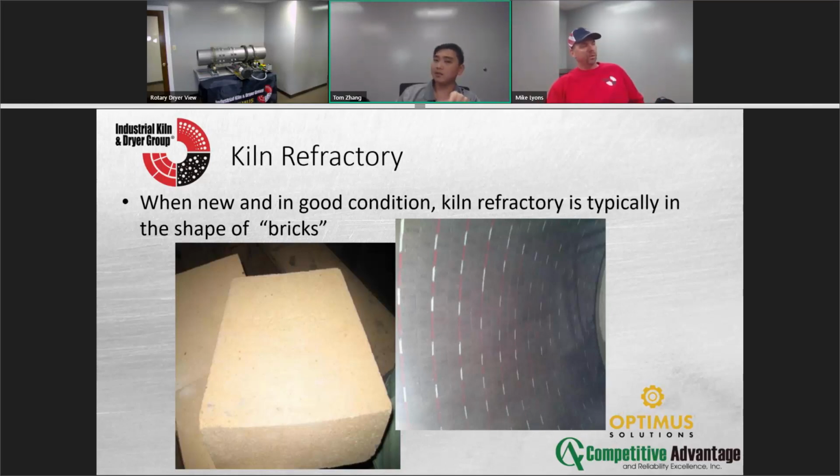I think I talked a little about it last time. You did. Make sure to look at your loads, because on a kiln, your major source of weight is your refractory. On a dryer, a lot of your source is the material itself. Right. So comparison, a kiln, a similar BTU kiln is maybe 30 tons an hour. A similar dryer may be 200 tons an hour. On a kiln, it may be 200 feet by 9 feet. On a dryer, it may be 8 foot by 30 feet. So it's a very different set for the same amount of energy.